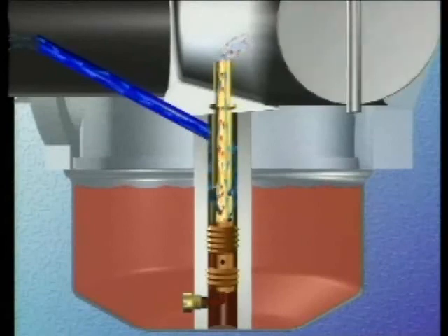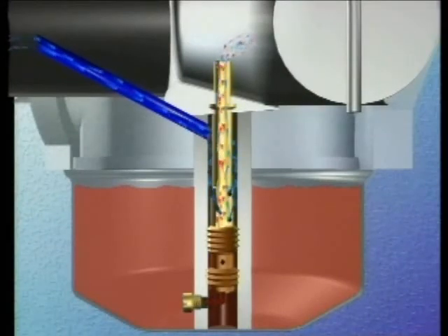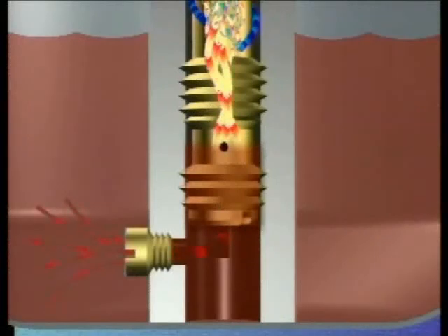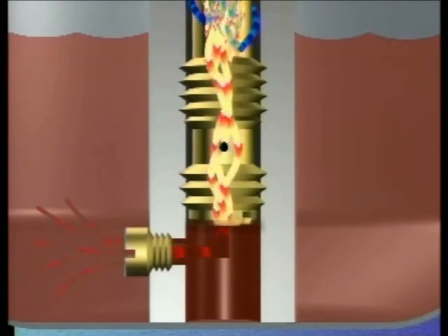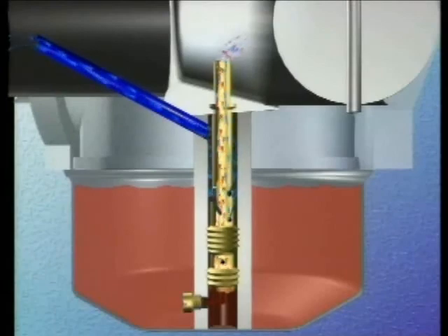Our 4th example is when the throttle plate is wide open and the engine is doing all the work it can. The engine needs the maximum amount of fuel that can be supplied through the jet. As a result, the fuel level drops until there's essentially no fuel level at all in the emulsion tube. At this point, the fuel flows directly through the jet into the emulsion tube and is delivered to the venturi.